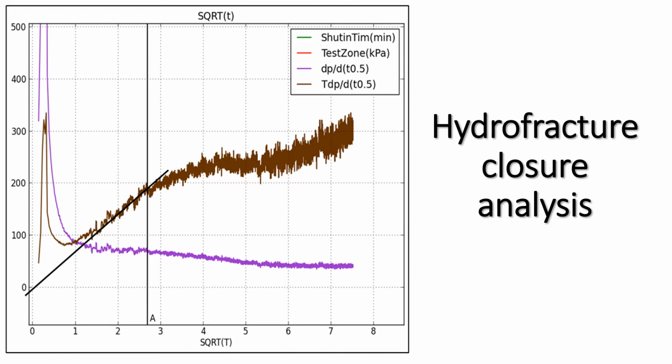The major stress is difficult to determine from hydrofracture. Most hydrofracture analysis is based upon the axis of the borehole being aligned in the plane of the minimum principal stress. It also relies upon the assumption that the rock behaves in a linearly elastic manner and is homogeneous. These are conditions that are frequently not met.